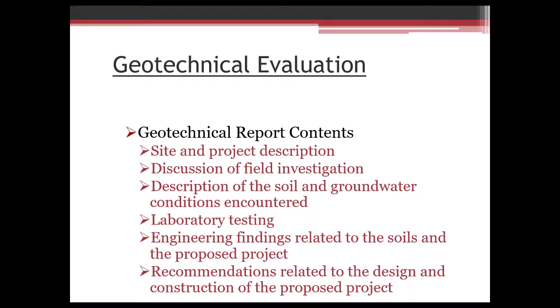So if I'm writing the report, generally I'll go to either the architect or the structural engineer to try to get some information on what the building is going to be, the size, the usage, maybe what type of structural system is going to be used, whether it's reinforced concrete masonry, maybe a concrete precast structure, or a steel frame structure. So those may need different parameters depending on different settlement tolerances, depending on how the building is designed.